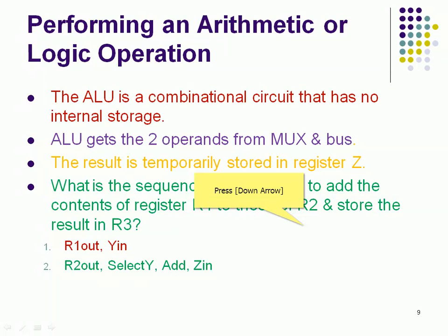Through the A point, select Y is there, no? Select Y. Since select Y and constant 4 are there, we can select either one, no? Here we want to perform this addition operation, and we have already dumped R1 into Y, no? So that's why select Y. By selecting Y, one operand is R1, so Y is representing R1 now.